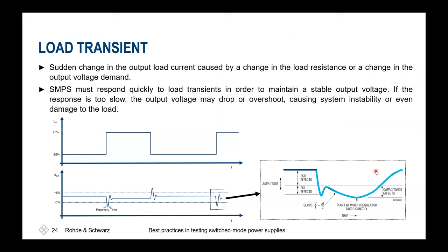What else to keep in mind? So if we're having a switch mode power supply, it shall power something. And at the end, if we have a system on chip, FPGA, ASIC, doesn't matter, and it starts to do something or anything, it will consume some current that's shown here. So the currents could jump significantly between the different values. And the jump in the current will immediately cause a drop in the voltage. And you, as a design engineer, have to ensure that your power supply is able to provide that amount of charge to get the current out to the system, and thus avoid also this voltage drop.